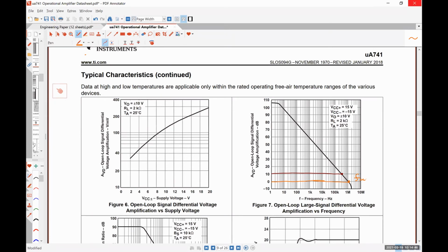So if you decrease the gain by roughly a factor of 6, what should you expect to happen to the bandwidth? It will increase by roughly a factor of 6. That's it. So there's a whole bunch of hippie math and crap in the book. Literally just remember gain bandwidth product is a constant and you can do everything you need to do, right?